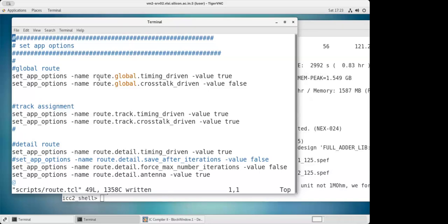A little louder, okay? Great. So now when someone is going to do their routing, first you are telling the tool that there are supposed to be tracks. Now if you tell the tool there are 10,000 wires you have to design, it cannot just design them like that. So again, there are 3 stages for the routing part: global routing, track assignment, and detailed routing.